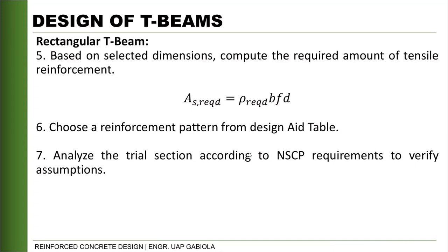If not, another value of phi should be calculated, but it should be noted that for a T-beam section, the steel will always yield, meaning the strain is always greater than our epsilon_ty or 0.0024 for grade 60 or 420 megapascal rebars.